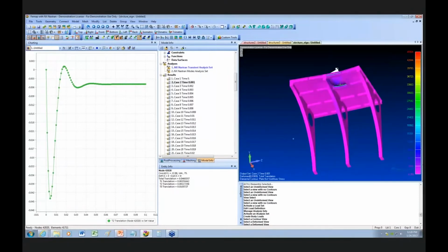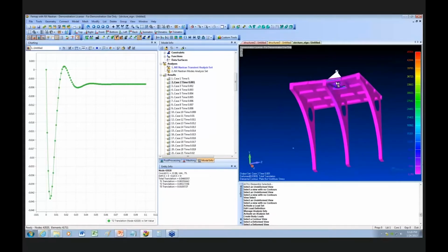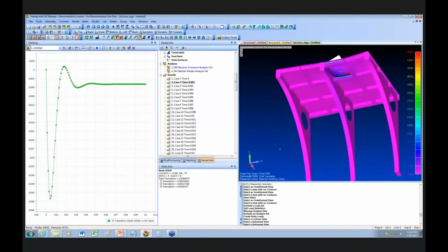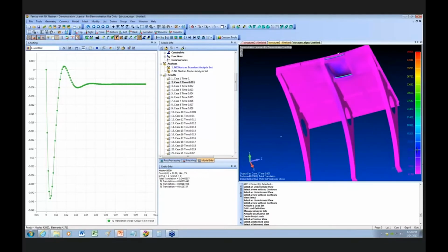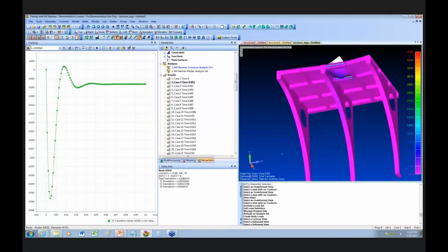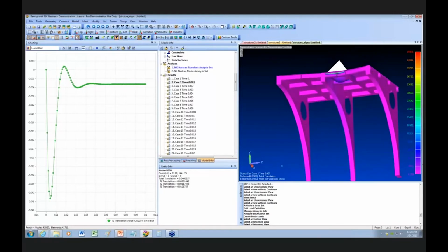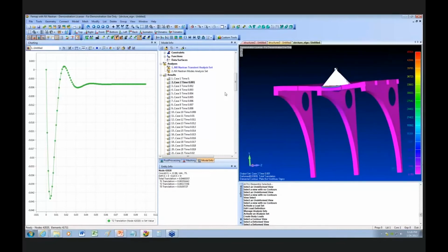But actually, what's happening is at the initial contact, the stresses or the loads are propagating through the structure, and I have an initial high stress right at the area of contact right here. I have a little high stress right here, but not a lot. It might be past, well, it's actually in the 1,000, but this is like 40,000 right here at initial contact. So as I go through this thing, you'll see the stresses start to radiate out from the impact.